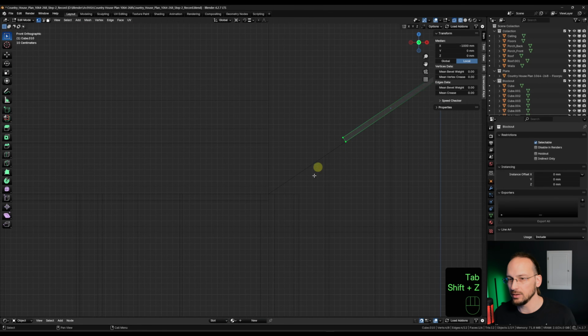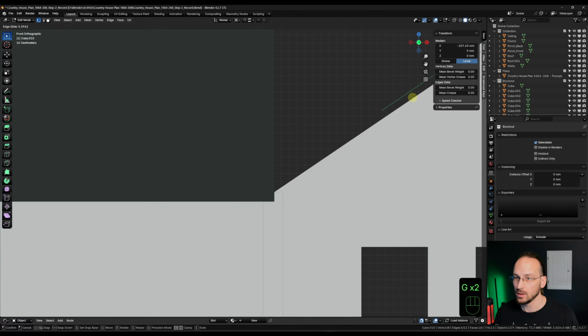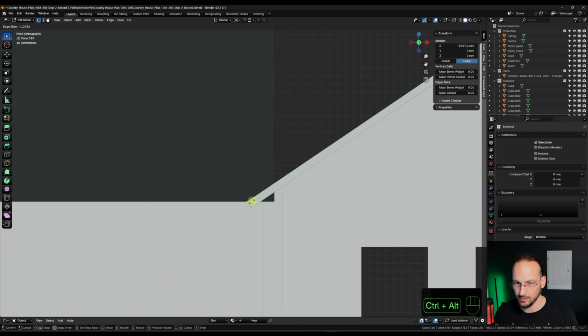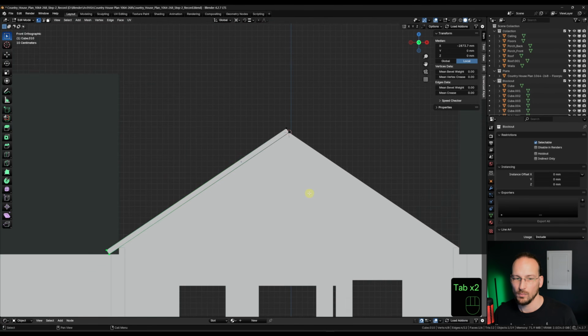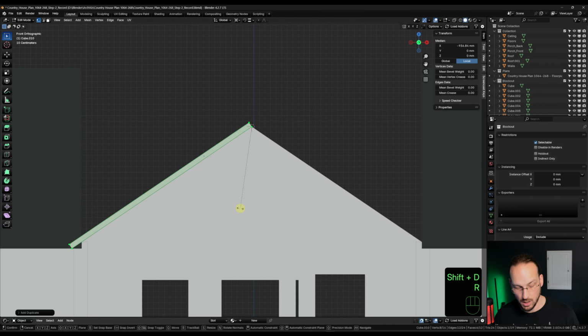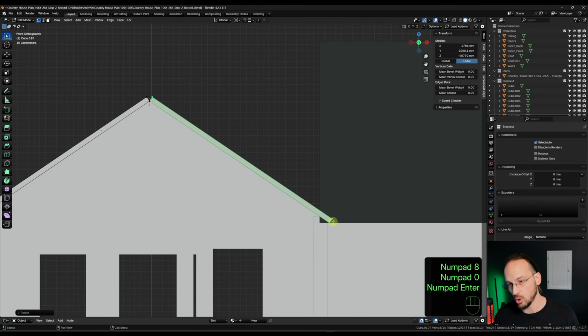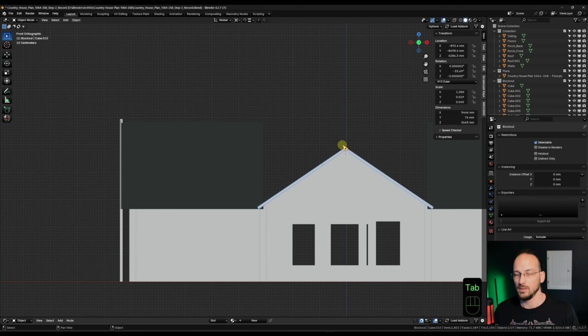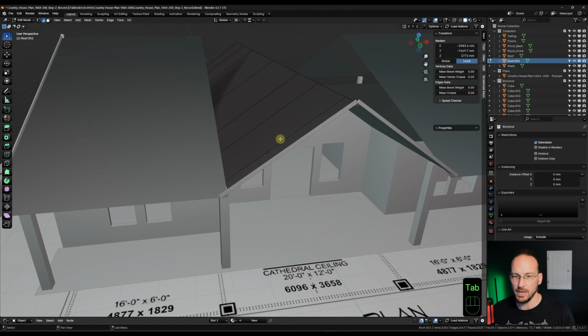And just like I did before, I'm going to switch over to edge snapping. Grab everything on the end here and snap it to the edge of our other roof part. So GG, hold Alt, and then snap it to there with the underside of the rafter. And again, same thing like before, A to select everything, Shift D, RZ 180. So we have that same option over here. Now back in object mode, select our roof part here and go into edge select.